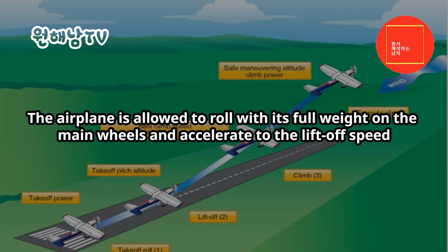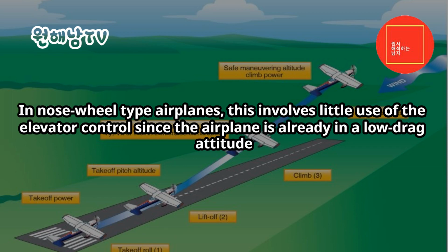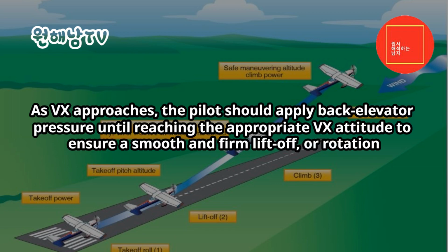The airplane is allowed to roll with its full weight on the main wheels and accelerate to the liftoff speed. As the takeoff roll progresses, the pilot should adjust the airplane's pitch attitude and AOA to attain minimum drag and maximum acceleration. In nose-wheel-type airplanes, this involves little use of the elevator control since the airplane is already in a low drag attitude. Lift-off. As Vx approaches, the pilot should apply back elevator pressure until reaching the appropriate Vx attitude to ensure a smooth and firm lift-off, or rotation.